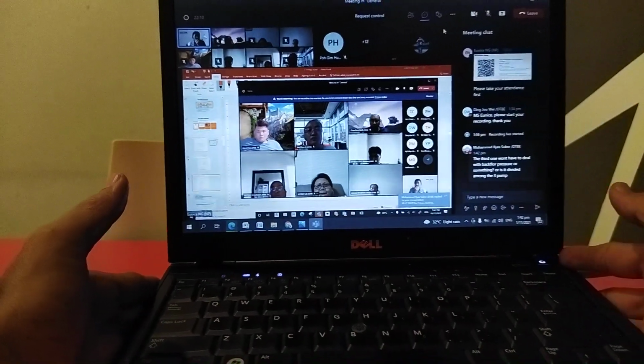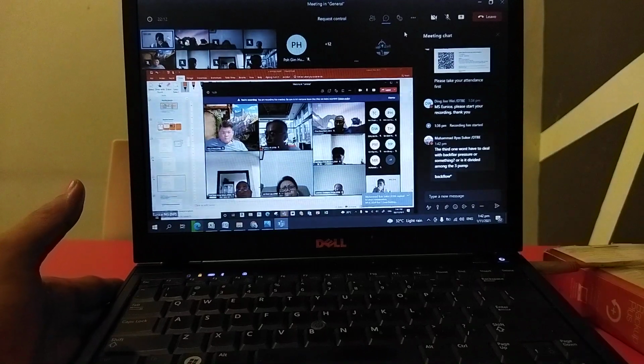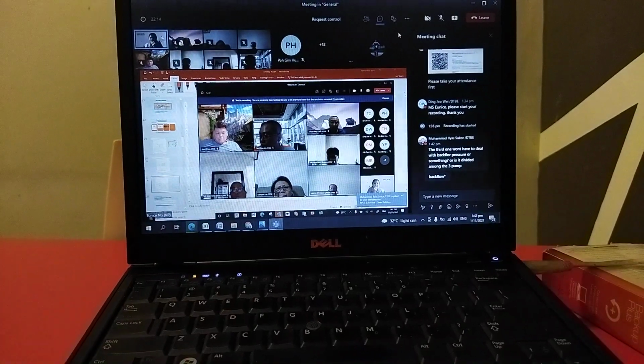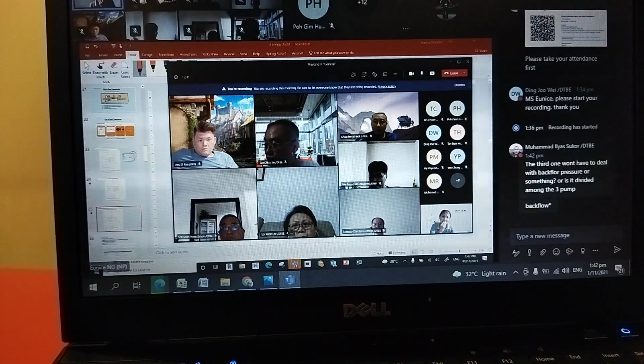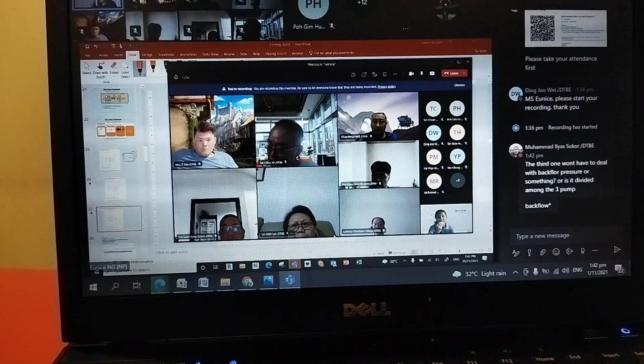If you have a downtown 50, 60 story building, you might want to have a separate secondary pump just to take care of the pumping towards the AHU, to the upper floors. I hope I answered some questions.